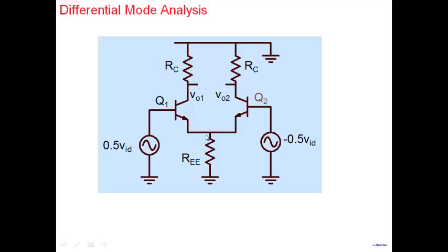If we look at this particular node, what do you think it will be? This node right in the middle. On one side you have positive, on the other side you have negative, and the middle node will be 0 because of the symmetry. It can't be anything else. This particular voltage will try to raise this value to a positive value here. This one will try to raise, will cause it to go to a negative value here. And therefore, because of symmetry, the two will balance each other, and the net value will be 0.